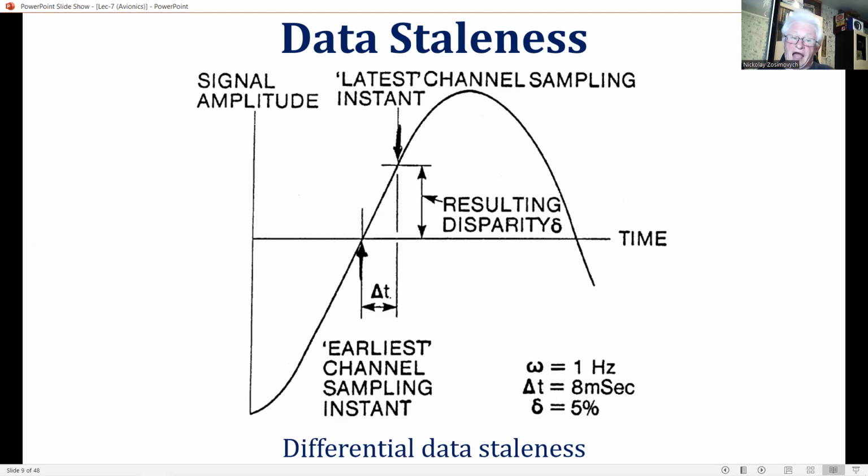Okay? And this results in a phase lag in the output, which increases as the frequency of the input increases. Look at this slide. Yes? Agree? Nice. The amplitude, however, is not attenuated, as with a simple lag filter, and so the destabilizing effect is increased.